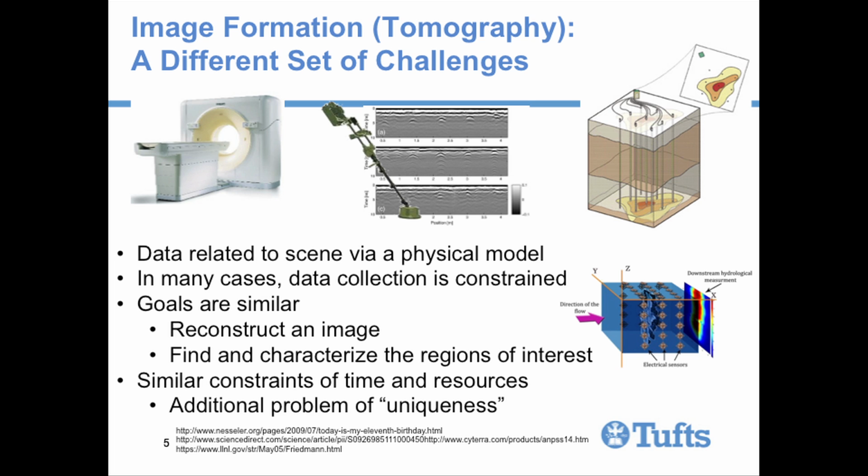And you can definitely see that there's something under the ground here. This is the ground surface. Is it a mine? Is it a rock? What can we tell? Here's an example of a different type of tomography problem. I think of these as tomography. This is electrical resistance tomography, where somebody bores holes into the earth. And the idea here is that I'm going to put little current sources along here and little voltage sources here, and I'm going to force electrical current into the earth. And I'm going to listen for the voltages at other boreholes. I'm going to change where the current is, I'm going to change where the voltage is, and then I want to build a map of the electrical conductivity in the region that's being interrogated.